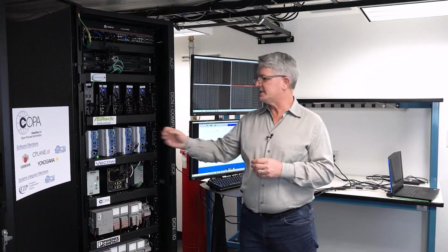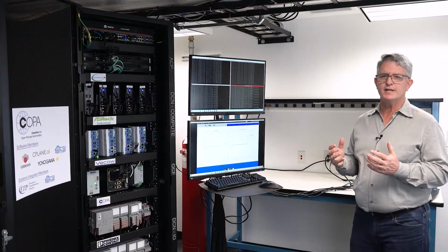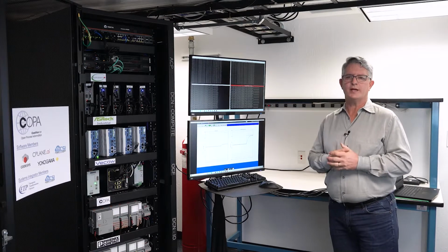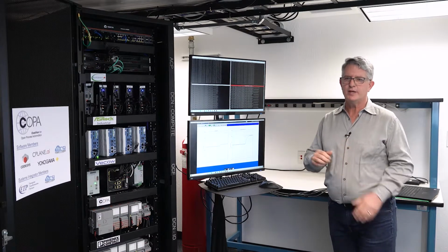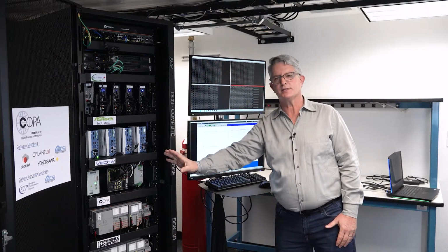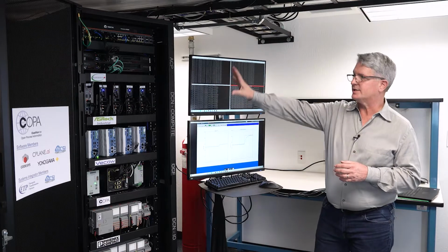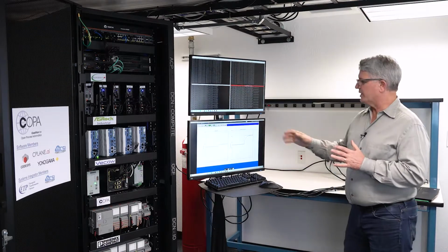And if there's a fault or connectivity issue related to the primary application's DCN compute node, as I said, DCN3, the control functionality will be automatically shifted to a redundant application that's running on another DCN compute node, in this case, the VCAL. We've created redundancy for this control application using software, not through one-to-one hardware redundancy. Just as a note, a secondary control application could be running almost anywhere in the QuickStart system, including up in the ACP. So we're at a new steady state.